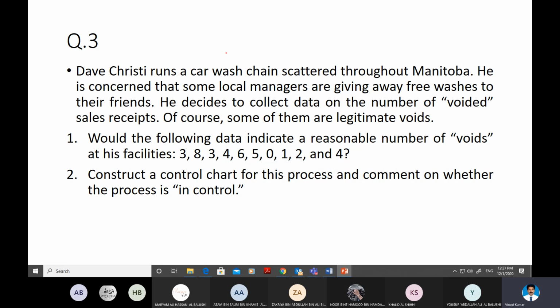As I told you, if you measure a dimension like diameter, length, width or temperature, it is an X bar control chart for variables, and an X bar and range control chart for mean and range. If you are specifying defectives, say out of 1000 items, 10 of them are broken, this is called a control chart for defectives, P chart.